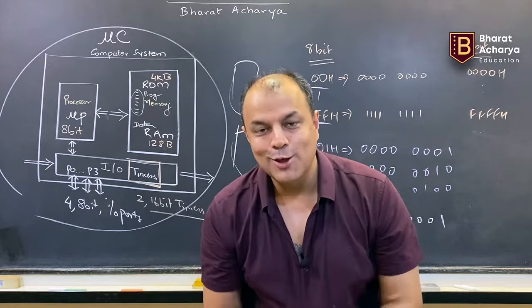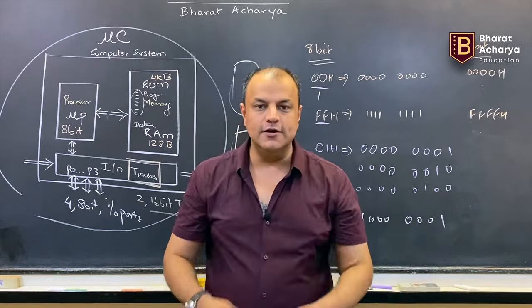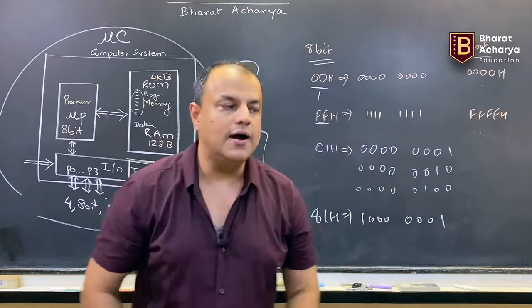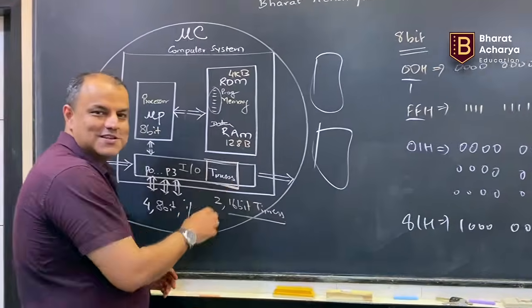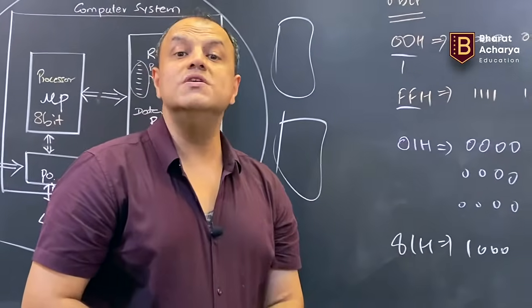For all of that, you need your processor to be free, which means you can't use a software delay. Here, you want to use a hardware delay. Hardware delay is where these timers come into the picture. Processor tells the timer, count 100. Who is counting?